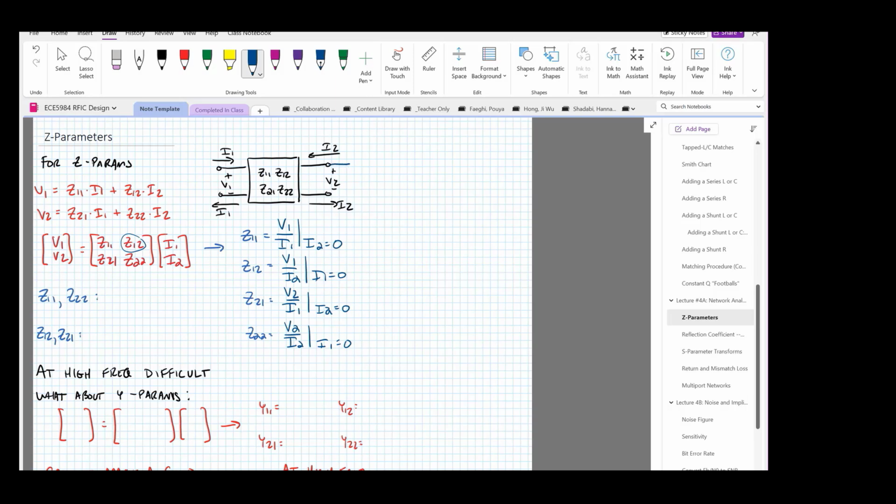So I try and put an open circuit at the output of the network. That just means I should leave this dangling, right? Ideally, I just leave this dangling. But in reality, if I put any type of probe anywhere near it or just a physical manifestation of the circuit itself, it's going to have some parasitic capacitance and probably some parasitic resistance. So I try and put an open circuit at the output, and I can't do that.